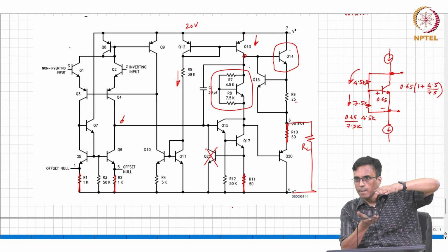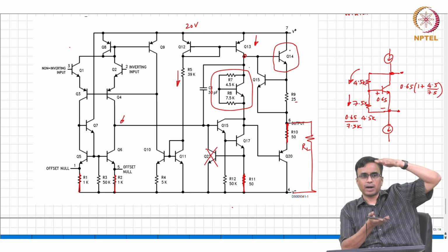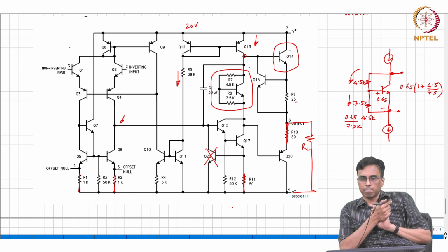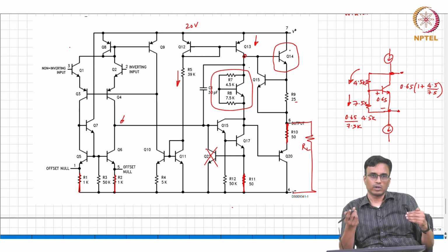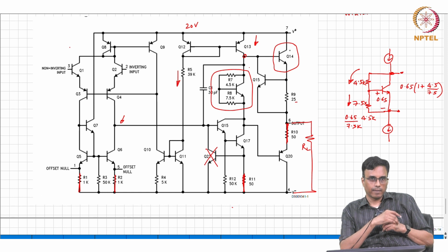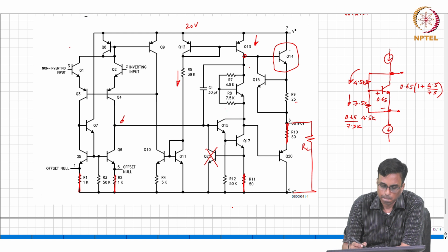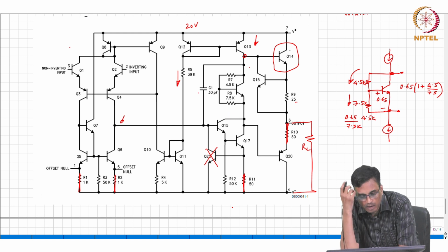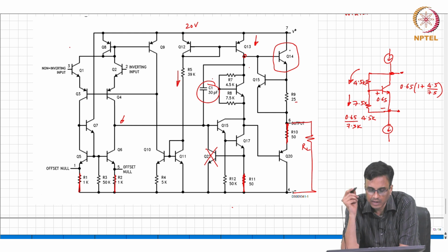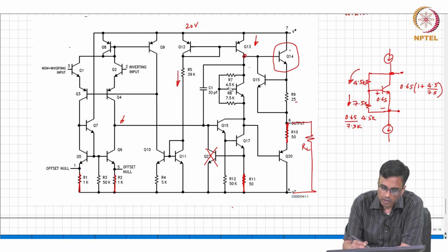conduct simultaneously, right. It is slightly smaller, so that only one of them conducts at any one time. So, the input goes positive, the NMOS transistor is pushing current, but when the input goes low, the PMOS transistor is pulling current. Okay. So, this is the equivalent of that battery. Okay. And CC is a Miller compensating capacitor. Okay. So, now the question is, why do you need all, what are these guys doing there?